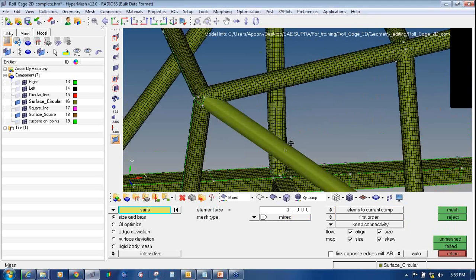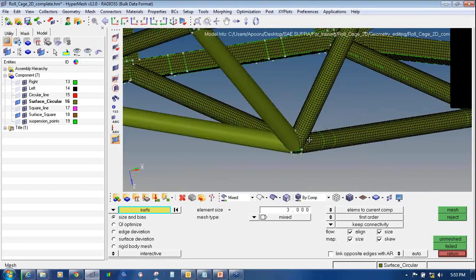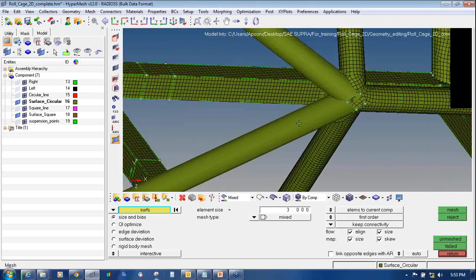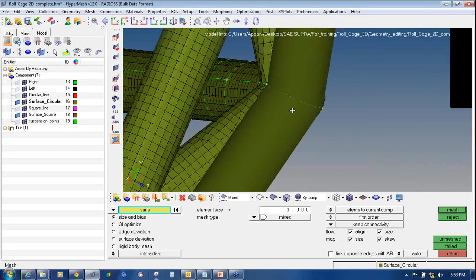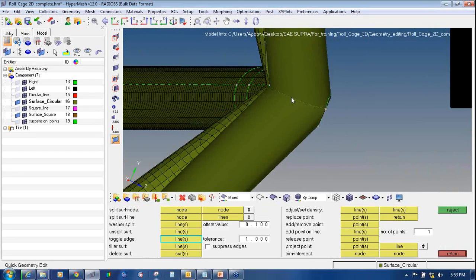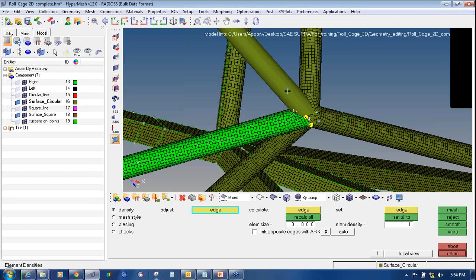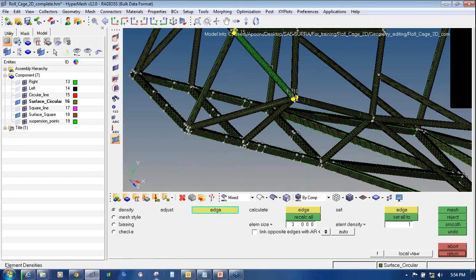So it has meshed, but it is saying one of the surfaces has failed, like this one. It is not generating the mesh on this surface. So we'll try to do the meshing. Okay, as you can see, this has been toggled down. So I will just toggle it, go to F12, and do the meshing on these two surfaces. Again, F12 is the shortcut for the auto mesh panel.